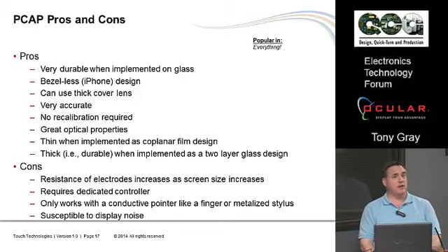It also requires a dedicated controller, which can be a downside. It has to have that because the algorithms to do the interpolation between the individual capacitance measurements are very complicated. There are some people who have implemented Pcap on a generic off-the-shelf microcontroller, and what they will sell you is their Pcap controller, but it's really just a Microchip part or an AVR from Atmel or whatever, and all they've done is added software to it.